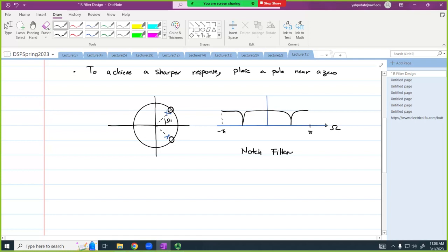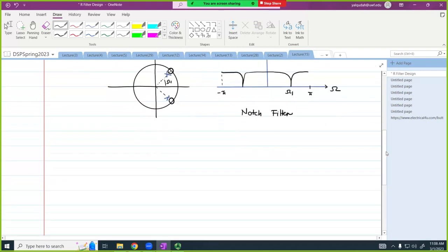So if I have a signal that, for instance, I recorded of a sensor in this room, I might pick up the frequency that's coming from the electricity. I might get a 60 hertz on top of that signal that I picked. If I want to remove that 60 hertz, what do I have to do? I can do a notch filter. It will just remove that frequency from my signal. And again, we'll do an example with some values that will illustrate this.